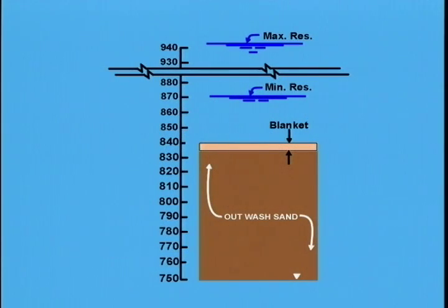Most of the bottom of the reservoir is covered with a 5-foot thick blanket of impervious material. In some areas, impervious glacial till was present and no blanket was required. The blanketed area is underlain by outwash sand. The groundwater table in the outwash sand occurs at elevation 750 feet, which is about 90 feet below the bottom of the reservoir. The sinkhole trenches develop primarily through the blanket. In one or two instances, however, where the outwash sand contained an appreciable percentage of minus 200 material, the sinkhole trench penetrated several feet into the outwash sand. During operation, the reservoir fluctuated from 100 feet to 30 feet deep.